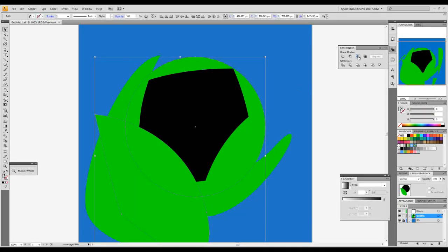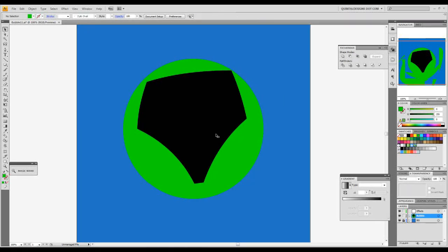And you can probably hear it on my keyboard. Tap, tap. Select, intersect, and you can see that that has just a really easy, really clean result. Tap, tap. And there's our bottom one, and all of our edges are done. Now, this is a little symmetrical, so I'm probably going to take this and rotate it to the side a bit.